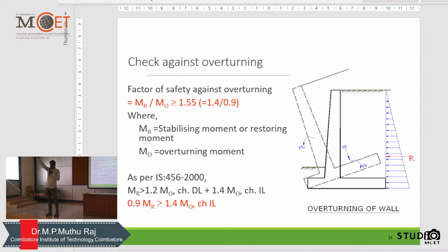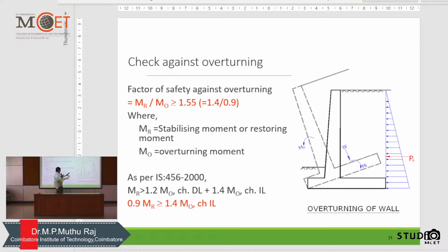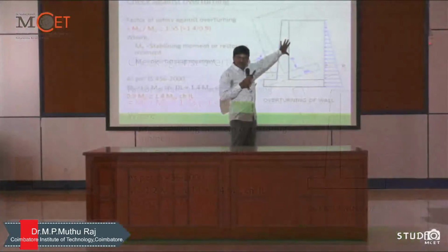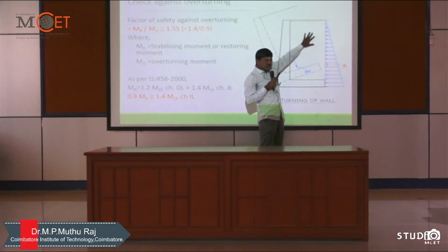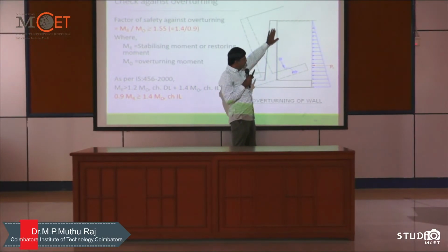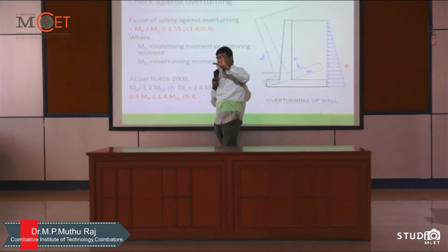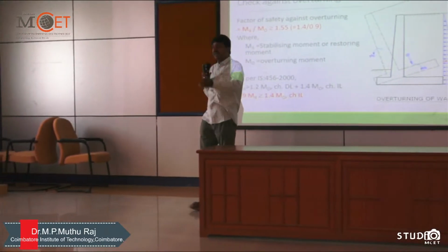When the soil is there in a particular slope or a heap, we have to break it in the horizontal direction. Just as a wall breaks the integrity of the soil on the side, similarly, instead of this wall, horizontally you just have a layer. That is nothing but a material or a fabric.